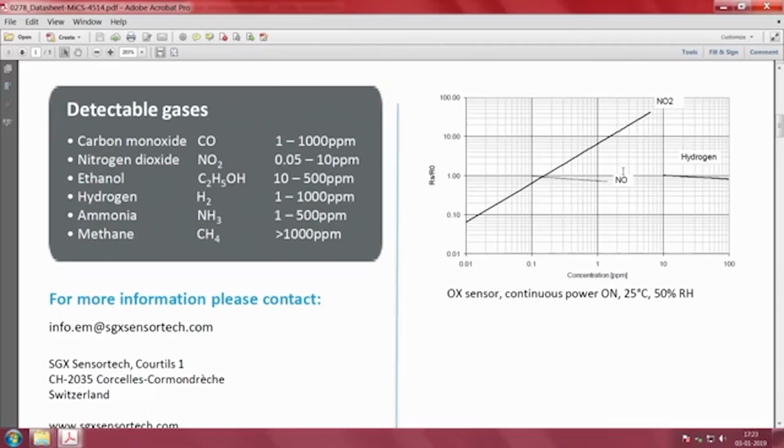Essentially that is what you could do all by yourself, but the professional way to do it is to take it to a gas calibration facility, which has mass flow meters and a climate chamber, and then there is a mixing unit, and there is dry air, and then there is the concentration of nitrogen dioxide that you want to mix together, and so on and so forth. So indeed all this is what you should be doing.